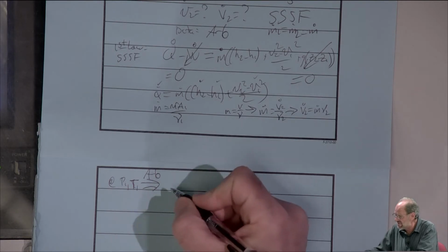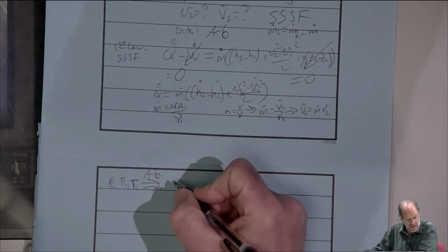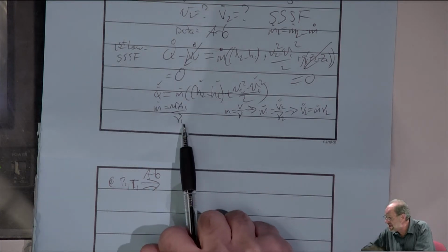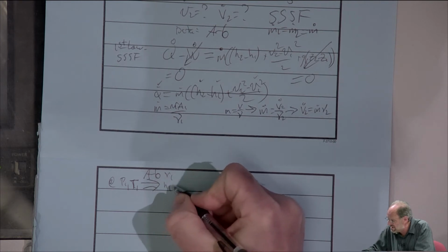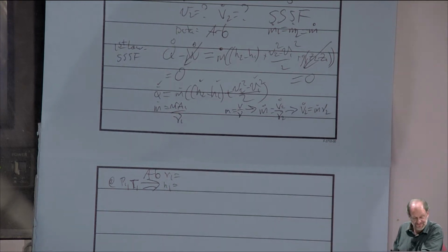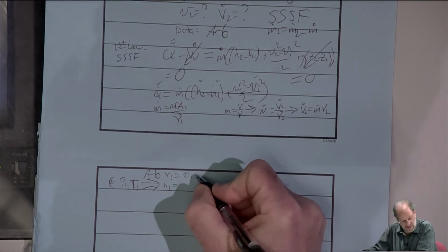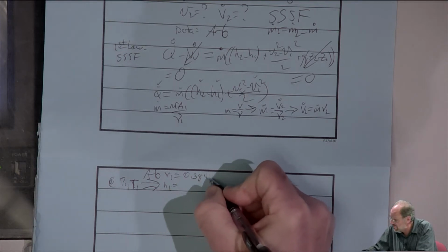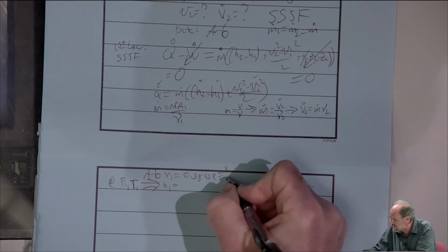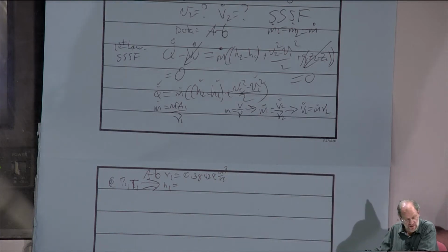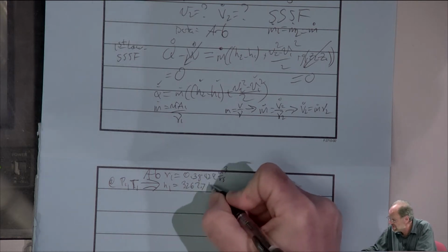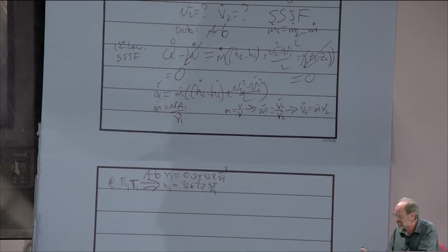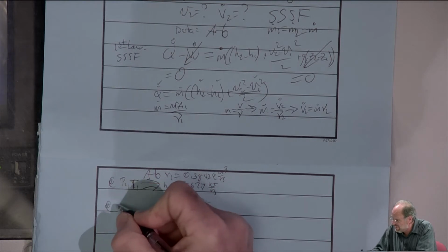All right, so we know this comes out of table A6. We know that we need specific volume data to find the mass flow rate, and we know that we're going to need enthalpy data for our first law. So v1 is 0.38429 cubic meters per kilogram, and h1 is 3267.7 kilojoules per kilogram.